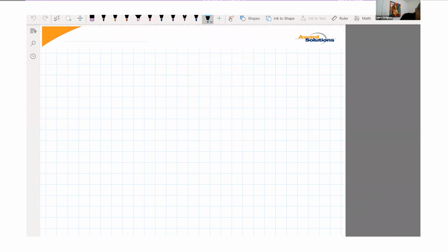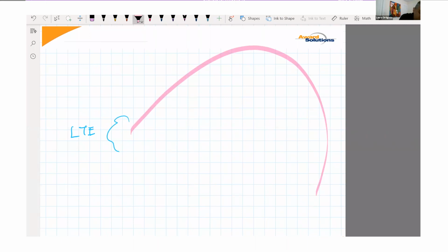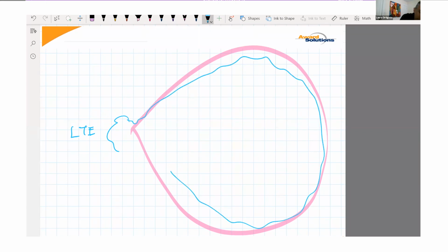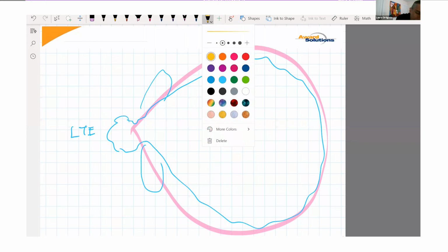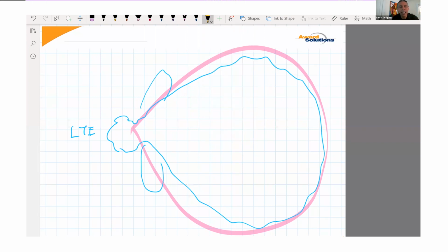So a beam is nothing else than a radiation pattern that only covers a narrower area, right? This is a narrow area. That's it. In this case, if I send energy to Alice, Bob will not be receiving it. Okay. Very good. So that's multi-user MIMO, guys, here. Multi-user MIMO, right? So how do we do this, guys? With massive MIMO. What's massive MIMO? Those cases where you have a large collection of subarrays, right? That's it, in short.